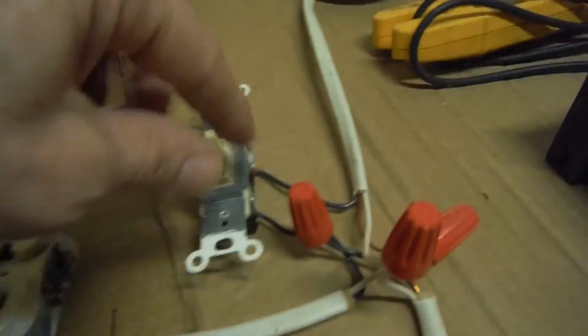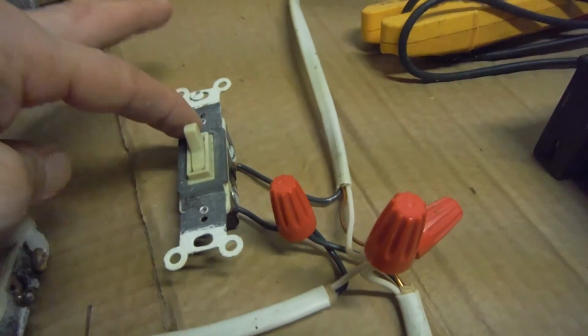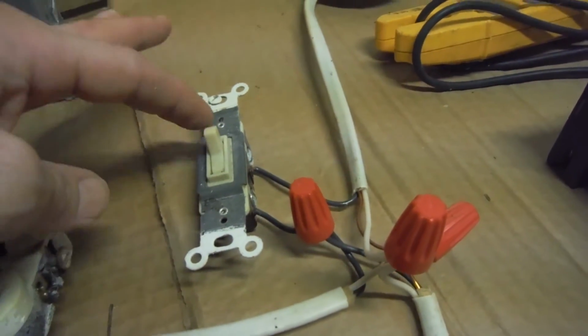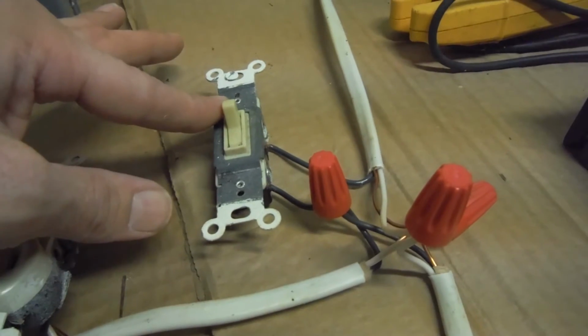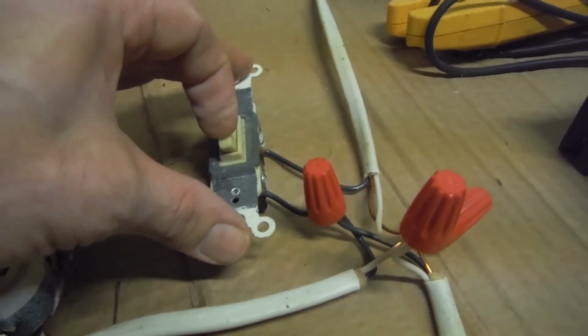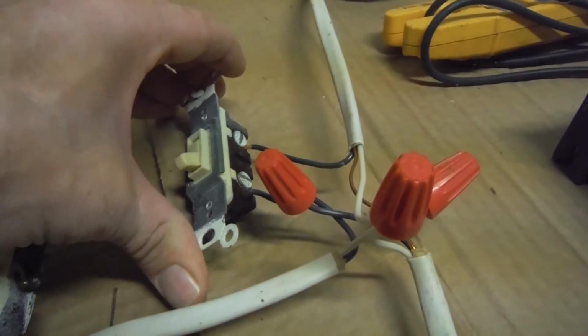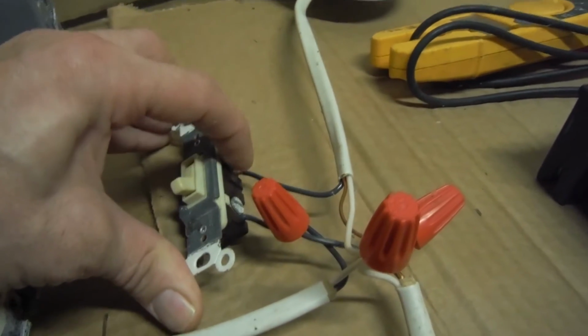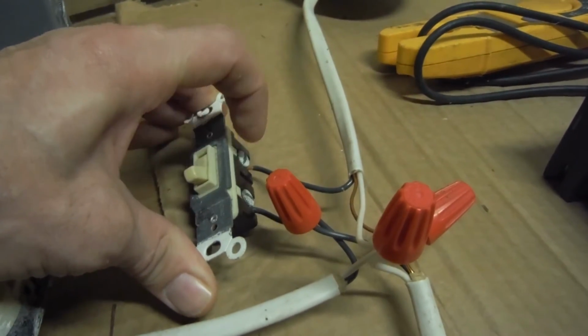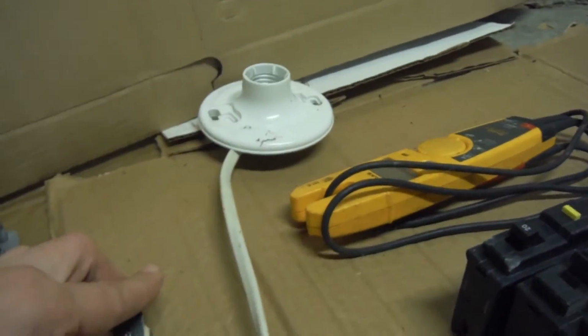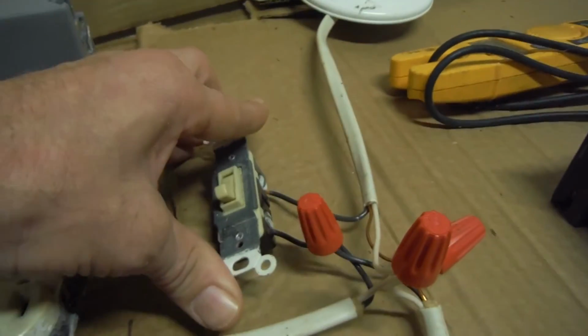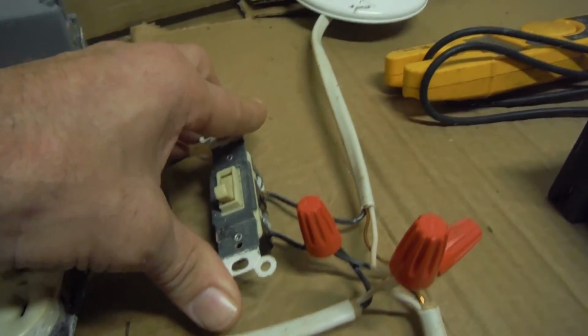If you were to suspect that this outlet, or this switch, was bad, and you were brave and disregarded all the warnings that I'm going to say in here, don't try this at home and all that, if you were to disconnect this wire and just touch them together, that light should come on, because you're continuing the flow of electricity.